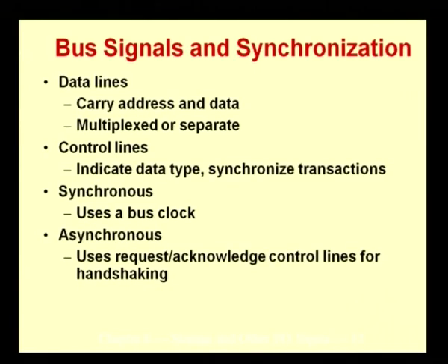Handshaking is a term that is normally used. So, when we talk of handshaking, it is normally used in the context of an asynchronous transfer, and it is similar to the handshake that we normally do, right, that one person puts out the hand and then another person puts out the hand in response to that. So, you can look at the same thing happening here, one device puts out a request and the other device responds by giving an acknowledgement. So, request and acknowledgement is like doing a handshake. So, which is why it is normally referred to as a handshake set of operations or handshake signals.